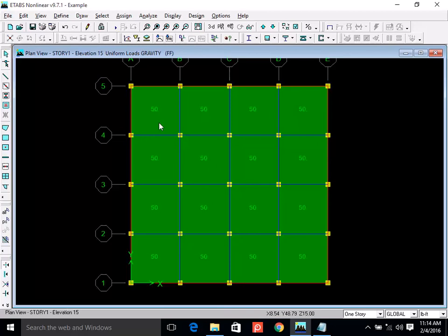So if you construct some wall here, maybe make a small cabin, or sometimes in the halls there are low height partitions, or small cabins, those partition walls apply the load directly on the slab. So you have to calculate those partition loads and distribute it over the slab.